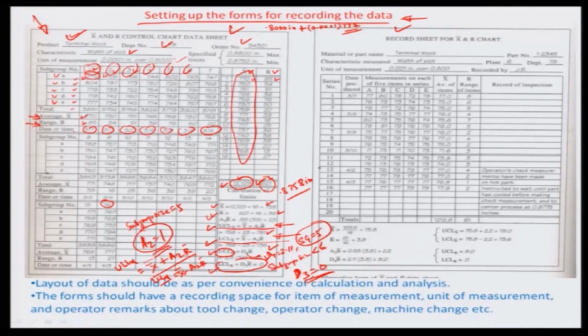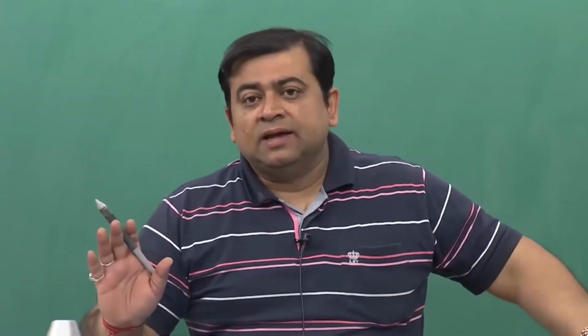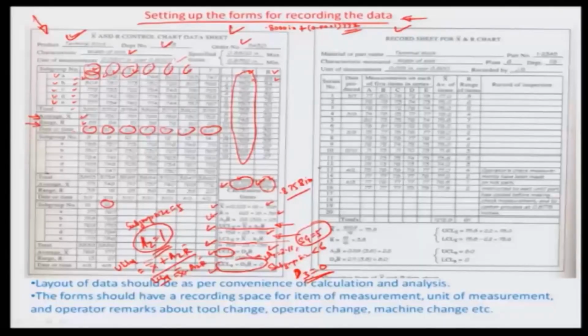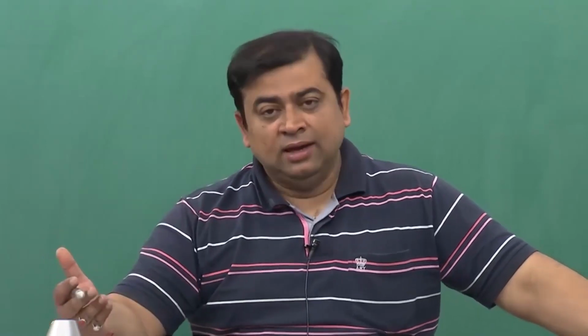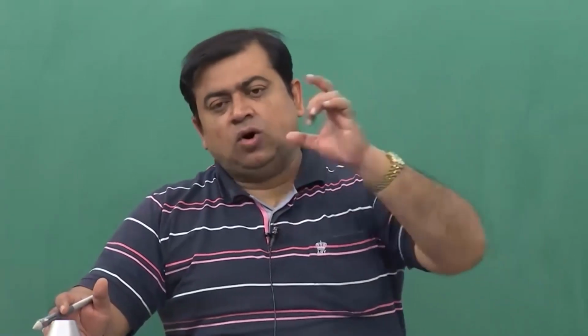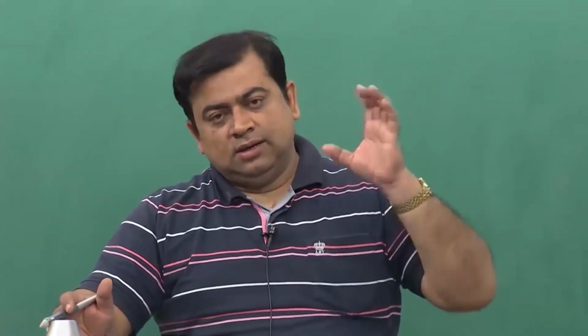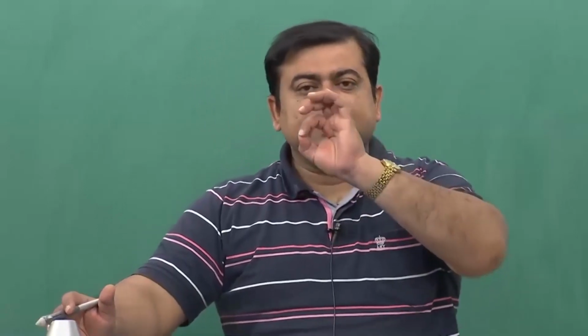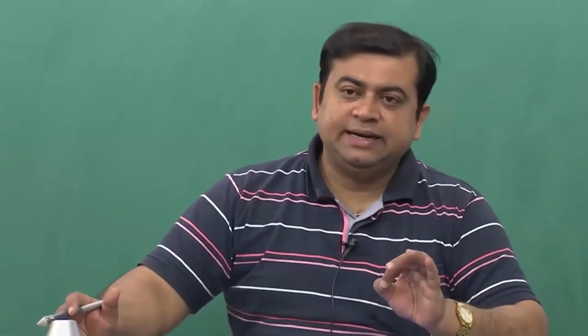So, you keep on plotting and extending the mean and range values in a similar manner. The only thing you need to change is the record form, from month to month: between April and May you will have one form, between May and June another. The mean and control limits are extended, whereas the separate points generated for each month's recording are extended on the same line.